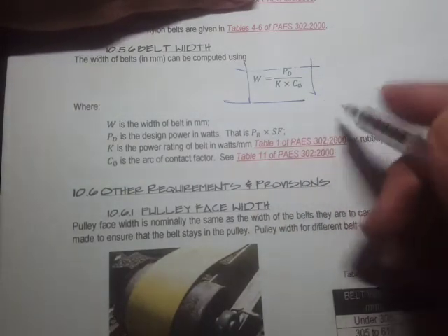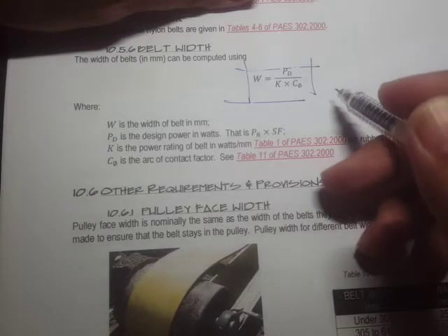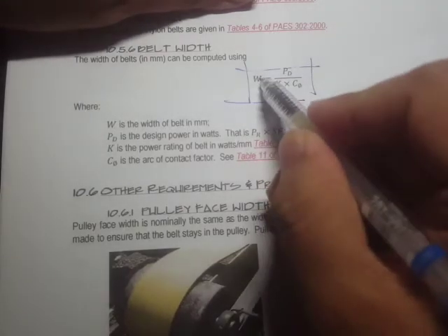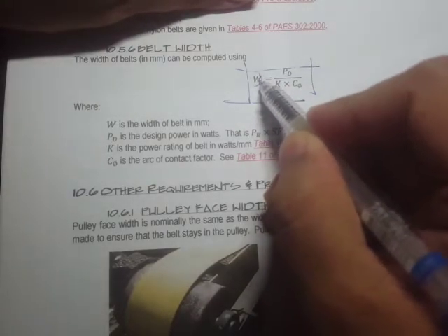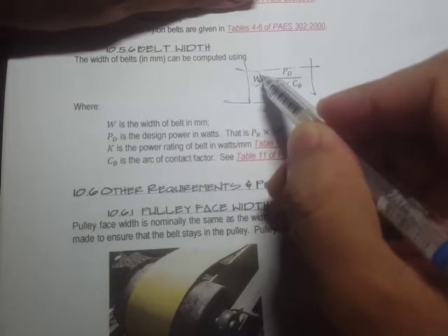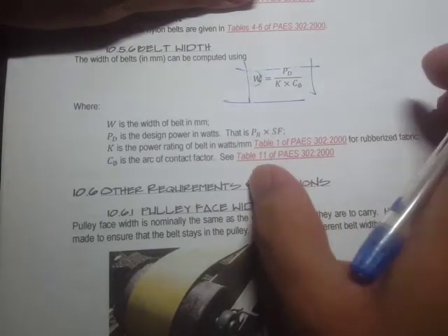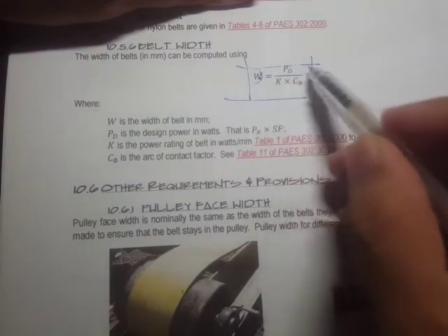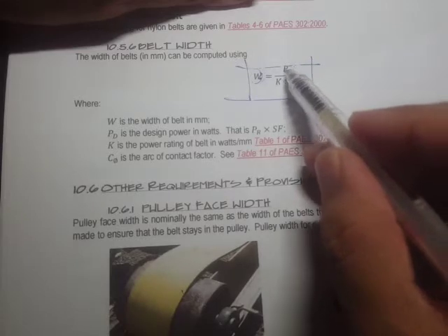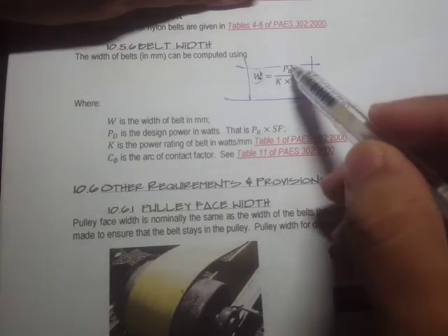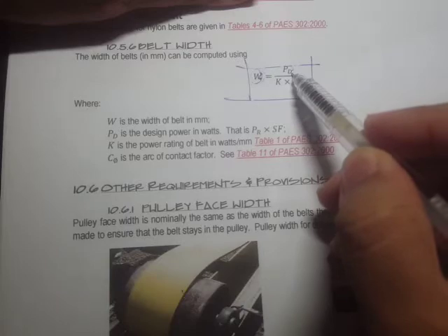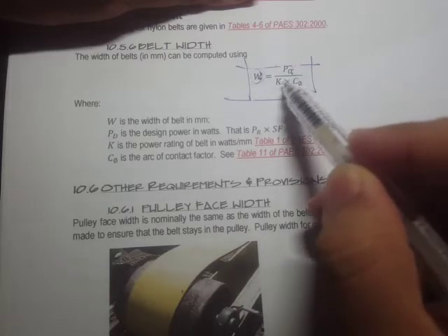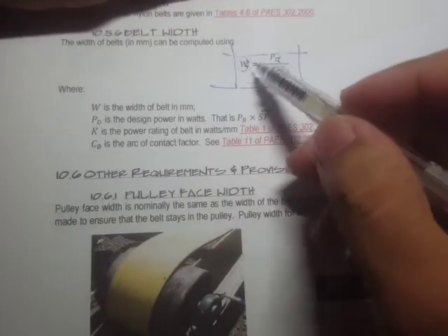And for the belt width, we have these equations. This is like how we know how many V-belts we need, but instead of the number of V-belts, this is in terms of width. So how wide would our flat belts be given this design condition, or this value for the design power. This is given by this expression, PD.